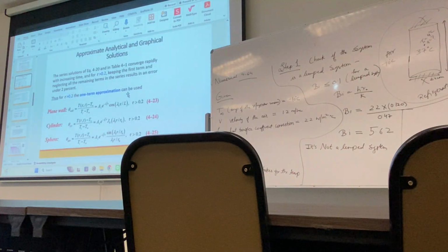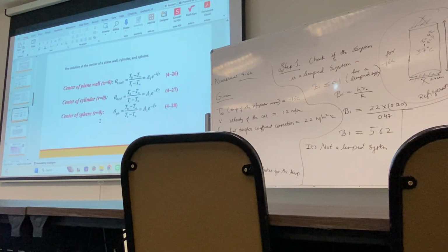You just have to look at the given quantities, what is given in your question, and see which formula you should use. This one, right? Because T0 is given in your question. It is the center temperature, right? We are calculating tau here, so we will use this variation.